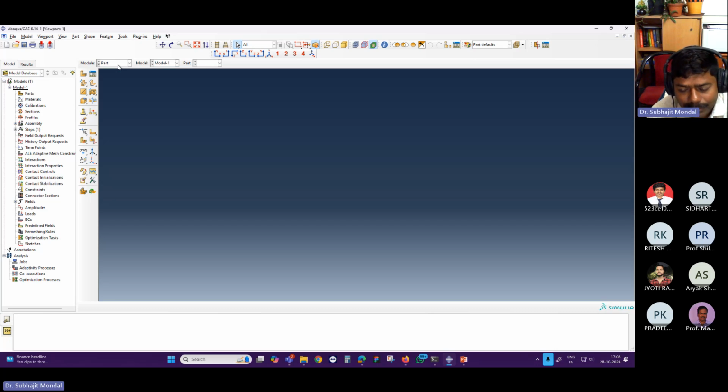and then you have to do the convergence study. You have to see how many elements are correct for you, how many elements give you a good result, and then you have to go for analysis. What type of analysis do you want to perform? So first is the modeling of the geometry. Next is the modeling of the material, whatever material you are using. There you can give the input of E1, E2 if you are doing an elastic analysis.